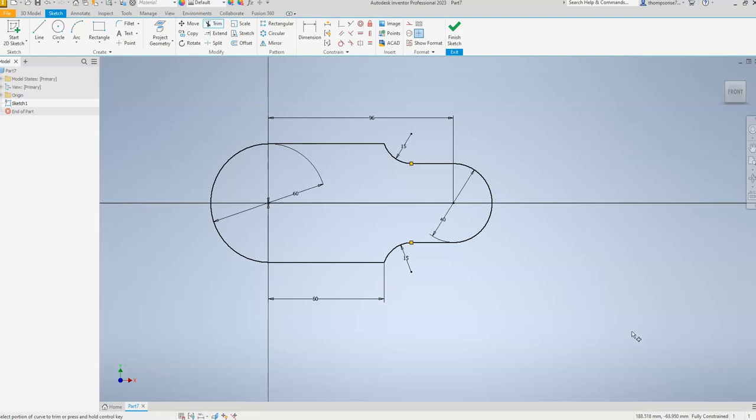All right, now we're going to put a few holes in. Align that because they're going to be concentric, and this has a diameter of 20. And then we're going to do another one at the other end. This one has a diameter of 20 as well. I'm not going to do the outer circle right now, the one that is a diameter of 30, because we'll do that in a separate extrusion. So 20, there we go.